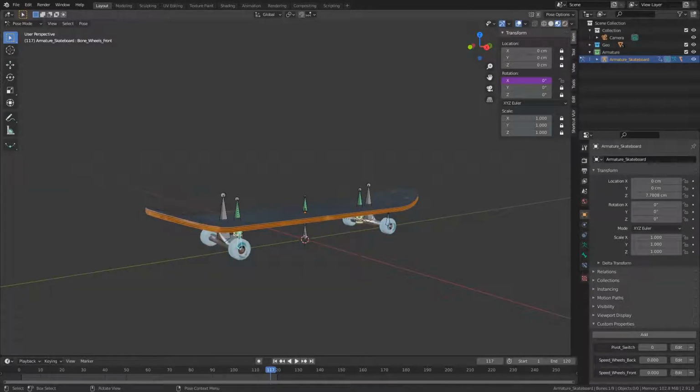Before we do the second cleanup phase, we want to create some custom shapes so it will be easier to control the rig and that it will look nicer. In order to do that, we are going to use an add-on called Orient Bone Shapes by Scaredyfish. You can get it for free on GitHub. A link to that is in the description. You don't have to use it. I just find it makes things easier.